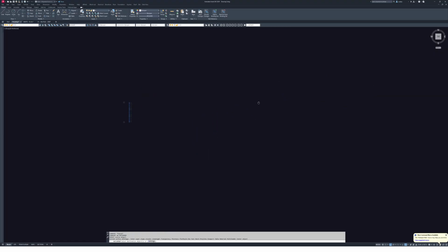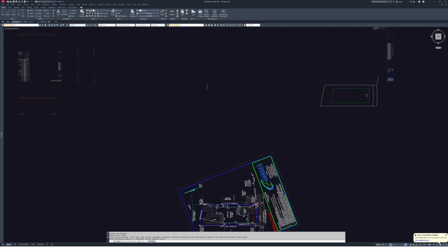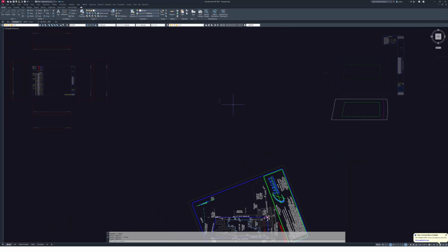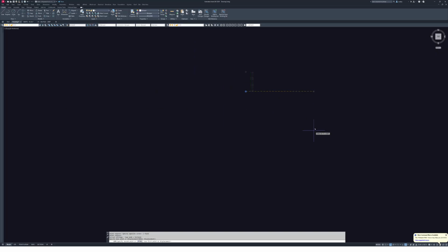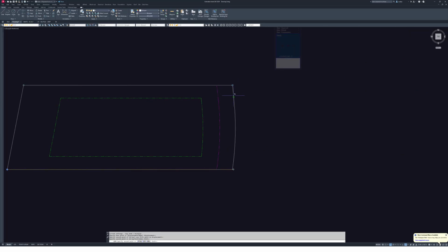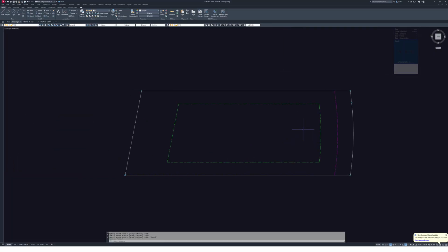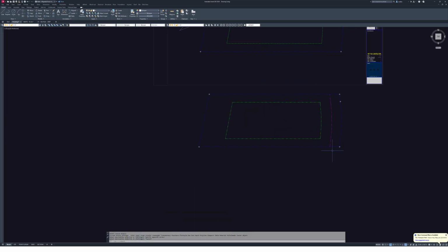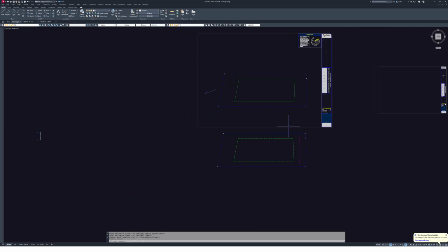we can match that. And I think I said I used my magenta for easements. And we'll erase this, and let's copy these nodes. Because it's grayed out, that means it's actually not part of the block. So we'll select it and say add to working set. And now it's part of it. So we'll copy and move node, node, node, and node. And then SR to save. And then we can match to put this whole thing back on. So there we go.